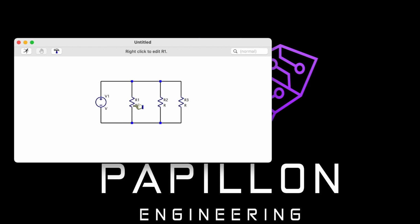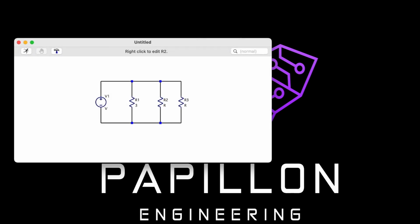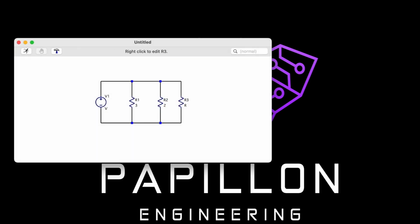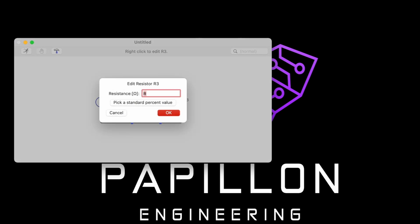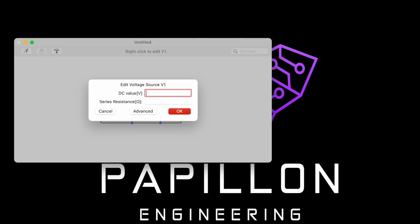Okay, so as you can notice, I hover my mouse over the resistor R1. You'll notice the words underneath the word entitled on the top toolbar. I also right click to edit R1, right? And that's when you actually enter in a resistor value where you see the units of ohms there, which is really important. So I'm using the same values used before, which is 3 ohms, 2 ohms, and 5 ohms in parallel. I'm going to use 20 volts this time.